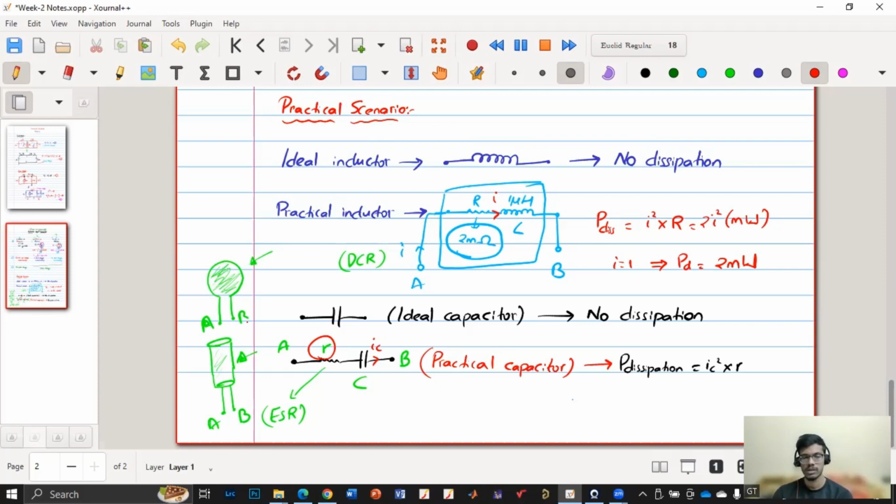So now, just getting out of this domain, I'm asking, how will I know how much resistance is there? There are multimeters, as you know, which are used to measure capacitance, resistance, different types of voltage. Similarly, there is something called an LCR meter, which is mainly used to measure the inductance, capacitance, and the resistance of any device.